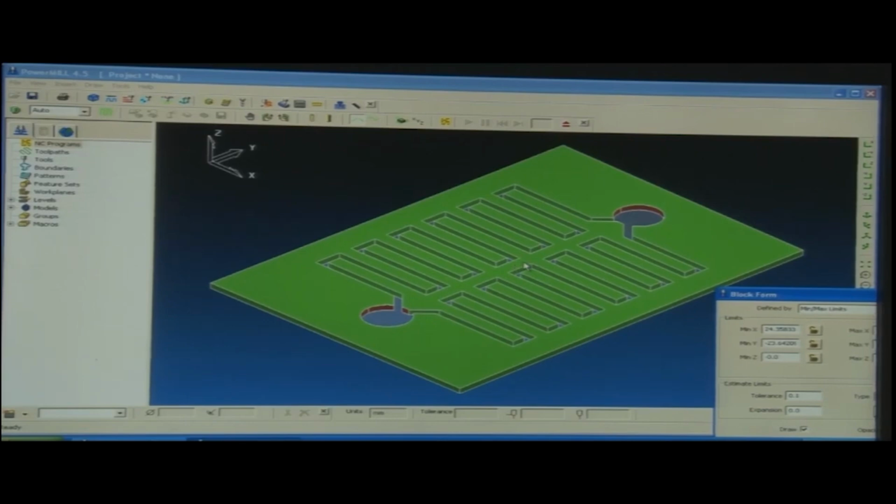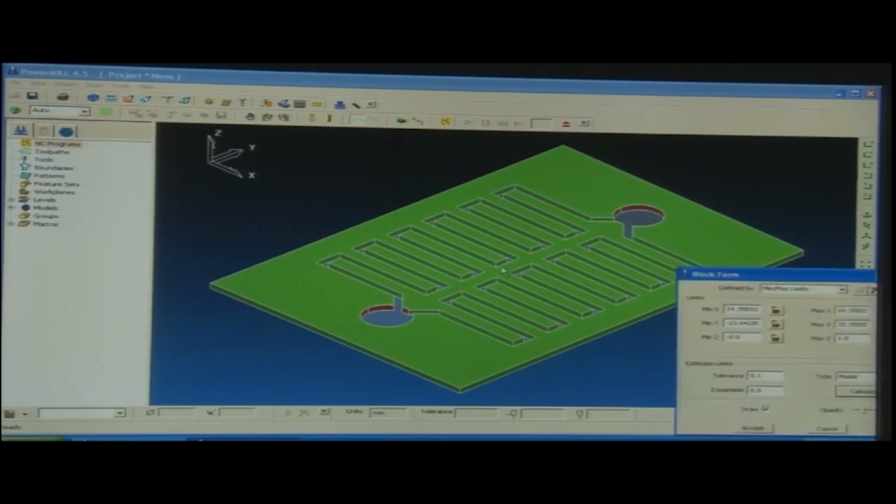Center would be the center of the x and the y direction both, and also the z, that is the perpendicular direction, the tool has to touch at the center of the workpiece. It is more convenient to take the center of the machine, because that helps us a lot, and also this job is symmetrical in both x and y directions. It is better to take the center.